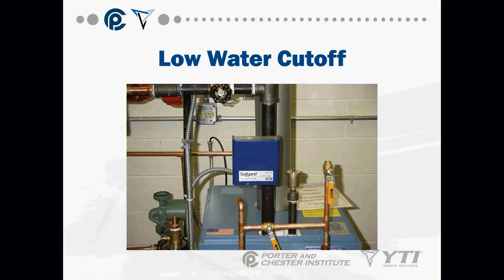Okay, and that's really what it would look like right here, this nice big blue box. It's going to be mounted right on the supply line, or in some cases it will be mounted right on the boiler itself. And really this is nothing more than a float switch. Water level has to be at least as high as the location of the low water cutoff. If that water level happens to drop below the location of this device, that boiler should not turn on. If it does, that low water cutoff is not working properly.